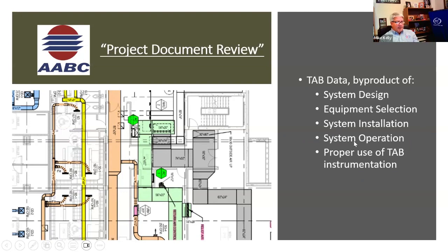If we design a system and it's, let's say, 10 ton, we know that's roughly 4,000 CFM, but we add up the system and it adds up to 5,800. Well, now we're expecting the unit to produce 20 or 30% more airflow than was designed. Why? What's the circumstance here? Is the airflow over because somebody established a dirty filter condition and there's going to be more airflow, and we want to end up at dirty filter condition with 4 tons? So we're going to expect 5 tons out of this unit, or it's 5.5, 6 tons down the road.